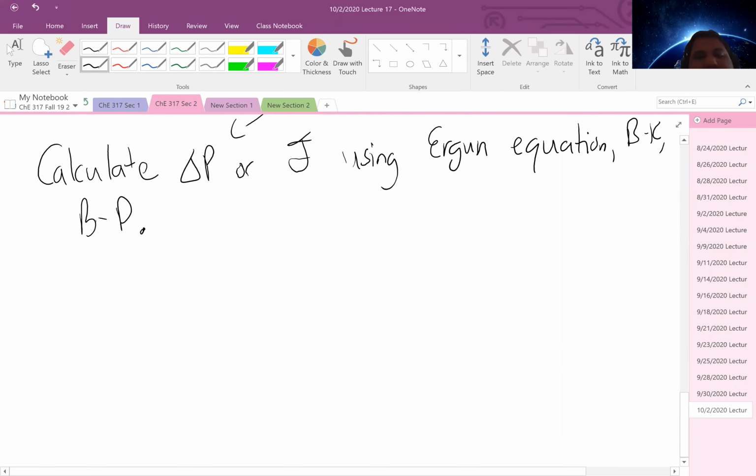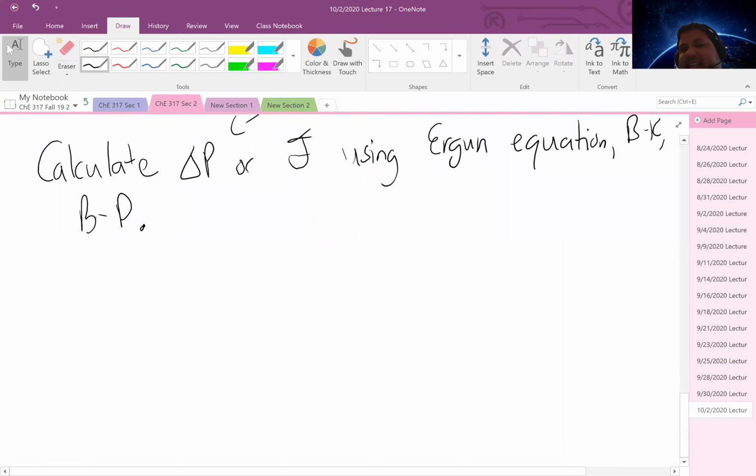And I think we worked an example problem associated with these at the end of last time, where we looked at a system, went ahead and used the full Ergun equation, solved for each term, and based on that, we found that the laminar flow portion provided essentially the majority of our expected frictional dissipation, and so the flow is most likely in the laminar regime.